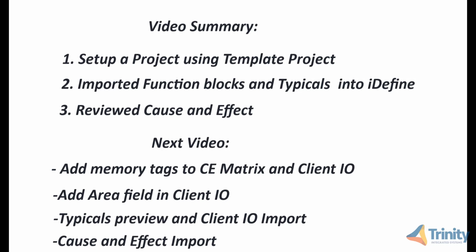Now you know how to set up a project using the template project, how to import function blocks and typicals into iDefine, and how to review a cause and effect. In the next video, we look at how to add memory tags to the cause and effect matrix and client IO, add area fields in client IO, preview typicals, and import client IO and cause and effects into iDefine.